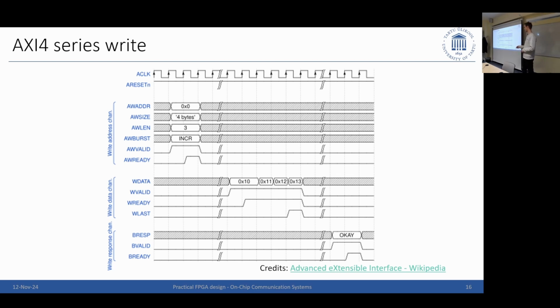In very simple terms. Very often I would recommend going to tools like Vivado. They will give you a wrapper to make an IP core into an AXI IP core automatically, so you can just click through that. That's also what the assignment is going to be around. So you have your design, and we put it all into the wrapper, and then we have to code it up a bit. We'll see how I facilitate that. That's not too much to code from a workflow point of view.